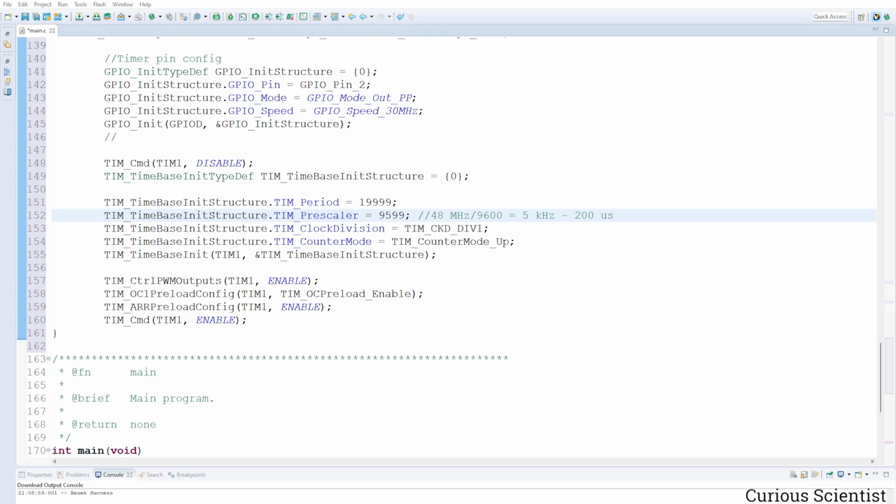So you can calculate backwards, and then based on this multiplier or parameter or factor, you can decide, okay, I want to count up to 1 second exactly, and then I want to do something. And how you do that is you divide 1 second by 200 microseconds, and that will give you 5000, which means that the counter has to count up until 5000 in order to do something. And we will do it like that.